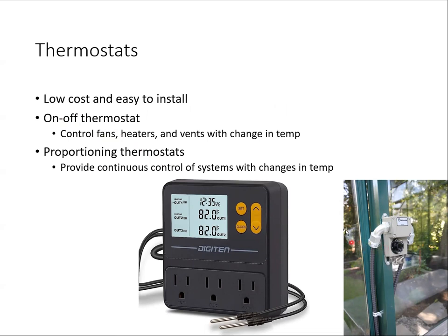If you need to heat the greenhouse, you just have a thermostat and a sensor in there that says, as soon as the temperature dips below 68 degrees, we need to turn on that heater until we get it up to 78 degrees. And then it will cool down until it hits 68 again, and then it will kick back on, and then cool, same thing repeatedly.